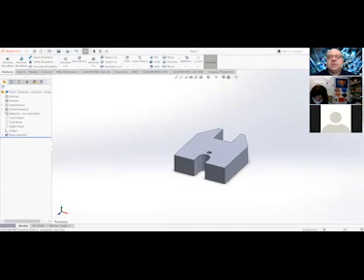And that's it. So you're still going to stay in the features tab for this. If you come across the top, you're going to look and look, and you're going, what can we do here? You'll find the fillet. So across the features tab, find the fillet. It's next to linear pattern. And then there's a down arrow. Switch the fillet to chamfer.